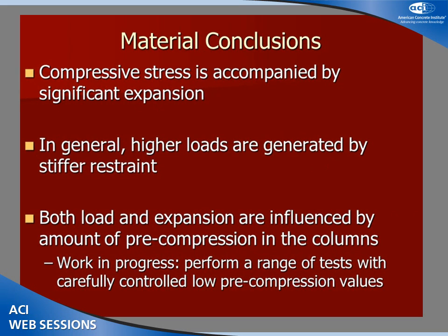Some additional conclusions. Compressive stress in every experiment was noted to be accompanied by significant expansion. There was no case where it was observed that compressive load or compressive stress was induced without expansion. In general, higher loads corresponded to stiffer boundary condition, and it was also observed, as I indicated in the data section, both load and expansion are influenced by the amount of pre-compression that's induced on the columns.